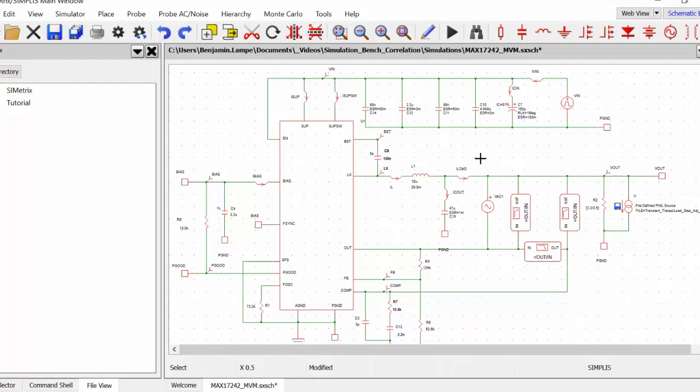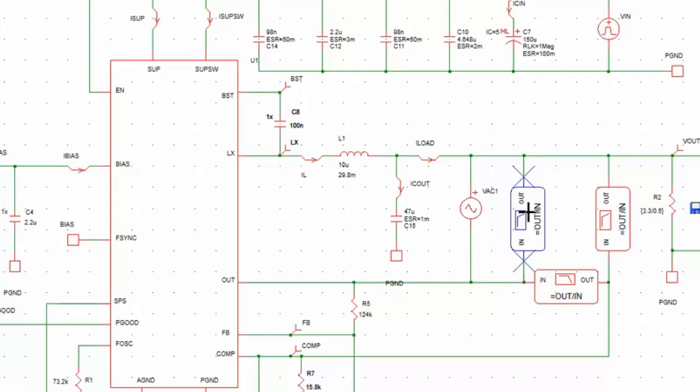So essentially this right here is what you'd think of doing when you're doing your normal AC analysis. You have an AC probe that's injecting a signal into your feedback loop, and then you have a measurement that's taking that injected signal as your input and the output voltage as your output. That is good. It gives you your full loop response, but when you're trying to go in and debug and figure out exactly what's causing what, it helps to have a little bit more granularity.